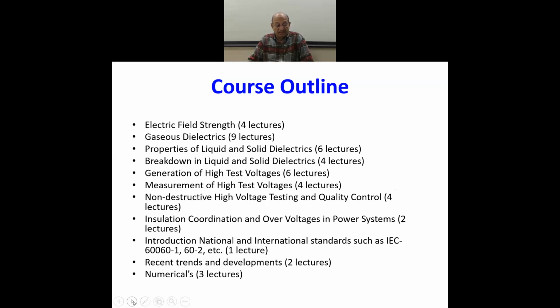And the tests performed in the laboratory are known as non-destructive high voltage testing of the quality of the product. This is non-destructive because in no way the test voltage should cause any damage to the insulation system. So that care is taken so that no damage is initiated in the electric system. So that is why it is called non-destructive testing.